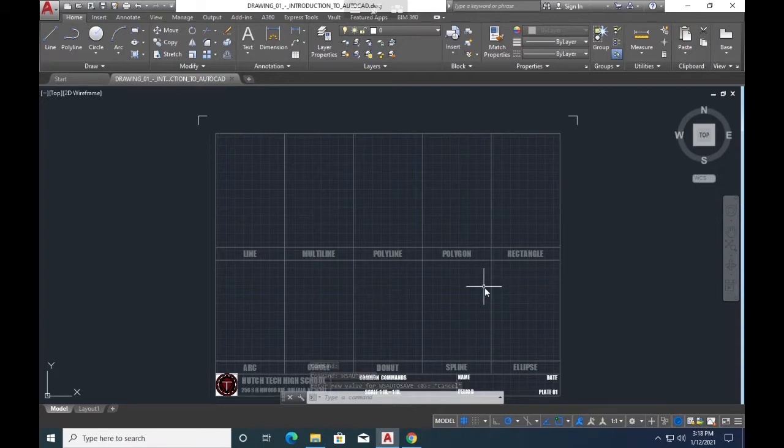So what I'm going to do is type in the following on my keyboard. I don't have to move my cursor anywhere. All I'm going to do is just type in the following. AUTOSAVE. Okay. Notice that it automatically has populated it right here. Auto save. I hit enter on my keyboard.